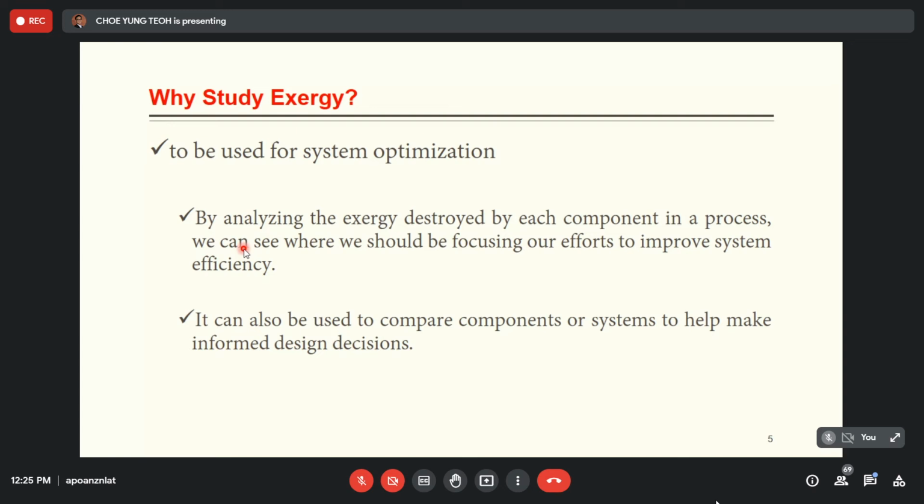So how can you count the energy that we can never extract? So when we check for the Exergy, we only check from the temperature of 100 degrees Celsius until the surrounding temperature of 25 degrees Celsius. After that, it's useless because it will reach thermodynamic equilibrium with the surrounding.